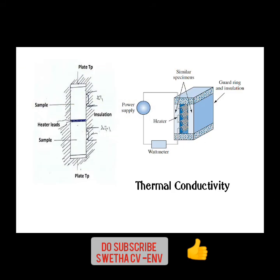So let's start with the last concept. In the case of instrumental methods, we have the thermal conductivity method. Its principle is that it measures the thermal conductivity of gases and vapors. Here the method has limited usage, why? Because it cannot identify the gas, but it only calculates the concentrations of the substances which are present in it, okay?